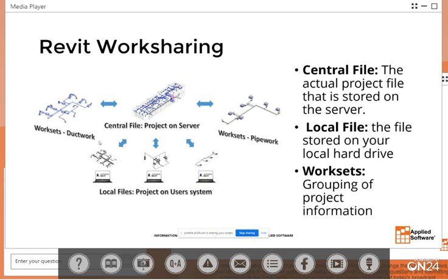And once it's saved and centralized on the server, everybody gets out of it. One person does this. And then say we have 5 guys on the team. Everybody then goes to open up the project off of the server, and they make automatically copies of it, it saves to their computer. It's built into Revit. I'll show you the paths.